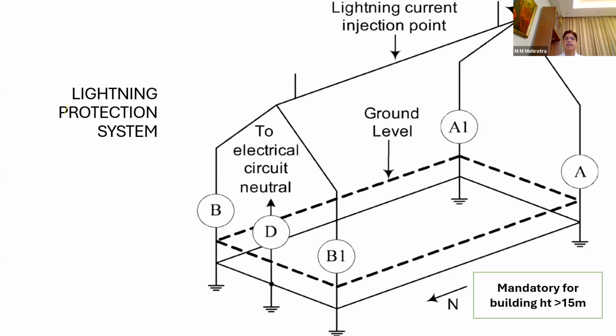So in lightning protection, we provide some exposed conductors at the highest point of my building. Here on the right-hand side and the left-hand side, you can see some features of the building. My conductor open to sky follows those features, so it must be at the highest point.